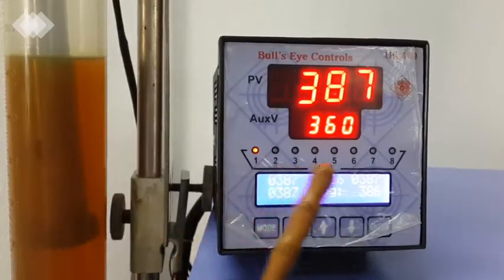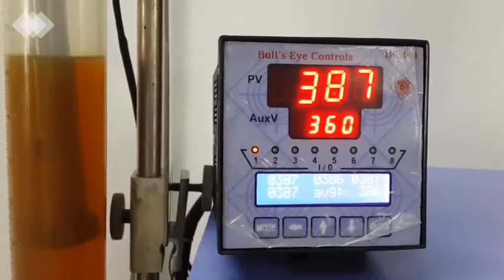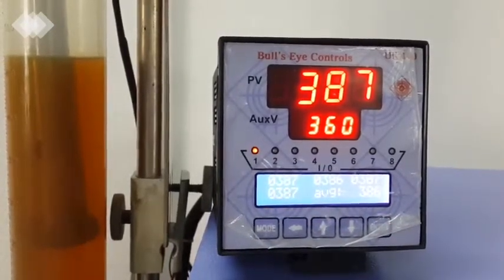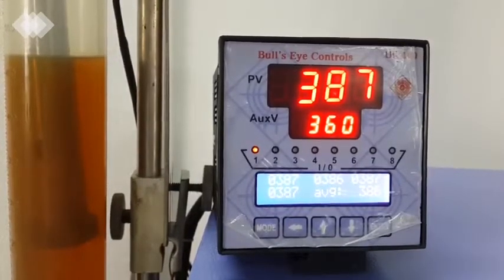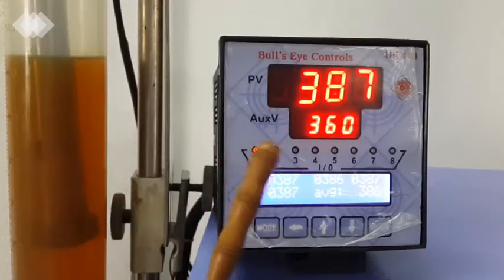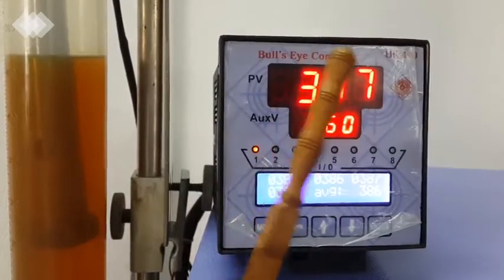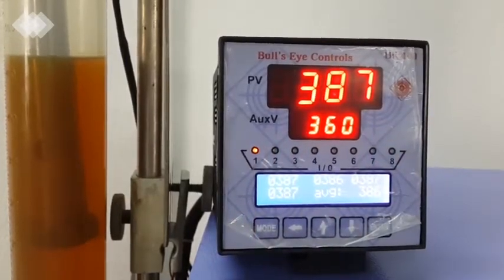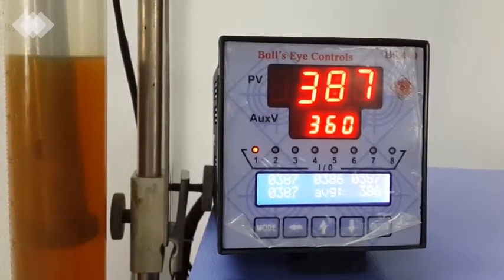So you can see now all the 4 readings are there, and now this will go on and on. If you want to see NOP, that is no operation, when it comes, you can just switch off your air supply and see that it attempts 3 times to take the reading, and if it fails, then no operation comes. The operator, from the alarm or from a distance, can make out that the air pressure has dropped. So he comes and adjusts it, and the instrument restarts itself.